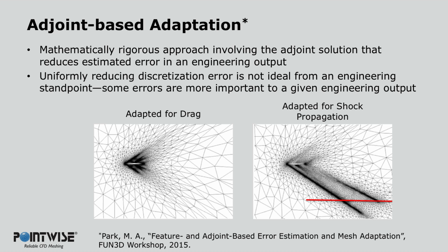Furthermore, one mesh configuration may be more suitable for accurately representing a given objective function like the lift-to-drag ratio, while another configuration would be used to reliably predict a different objective function, such as pressure drag. While a priori mesh quality assessments can be useful, particularly with flow solutions involving simple models where experienced practitioners can anticipate interesting flow features, oftentimes this can be difficult to accomplish when more complex geometries and flow physics are used in simulations.